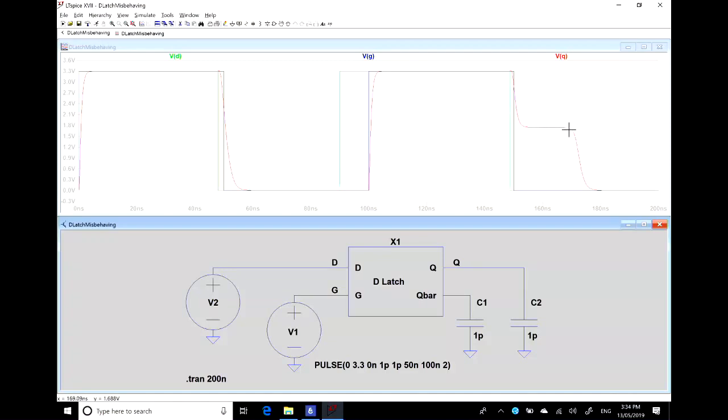They don't get stuck forever because partly I wasn't going to spend 5 years trying to optimize the time difference between here and here to get it just right, and partly because this computer uses floating point arithmetic and you'll get arithmetic errors. So no matter what you do, I don't think you can get it stuck halfway forever. Just like in real life, your flip-flop is not going to stay in the metastable state forever, even though it's theoretically possible, because any amount of noise is going to push it out.